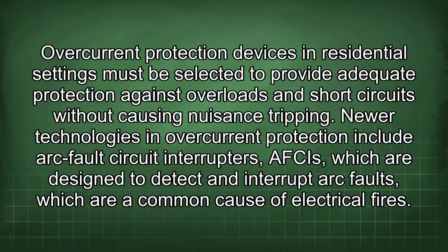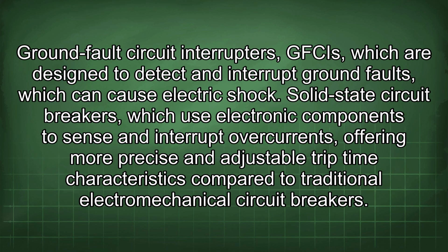Newer technologies in overcurrent protection include arc fault circuit interrupters (AFCIs), which are designed to detect and interrupt arc faults, which are a common cause of electrical fires. Ground fault circuit interrupters (GFCIs) are designed to detect and interrupt ground faults, which can cause electric shock. Solid-state circuit breakers use electronic components to sense and interrupt overcurrents, offering more precise and adjustable trip time characteristics compared to traditional electromechanical circuit breakers.